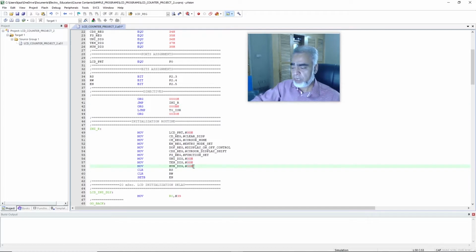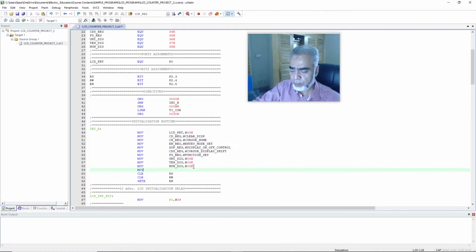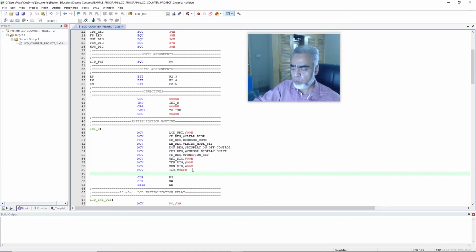So here we will write MOV TL0, #0EFH, and here we will write MOV TH0, #0D8H.